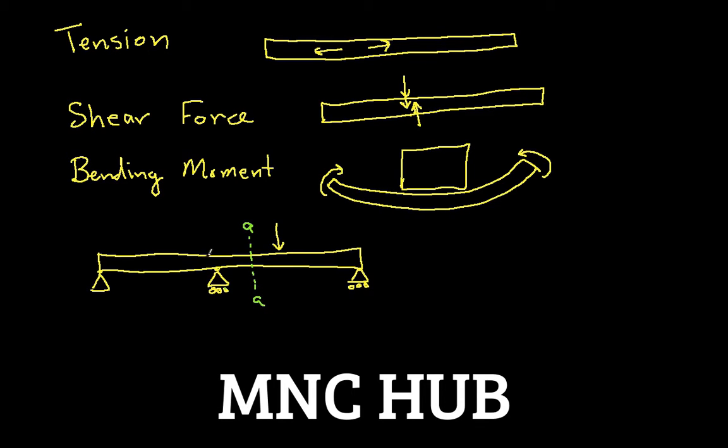So in this case, I'll call it cross-section AA. And we split the beam into two components, at least conceptually. So I'd have this guy here. I'd have reaction forces here and an upward force here, and maybe a weight force that the beam itself represents.